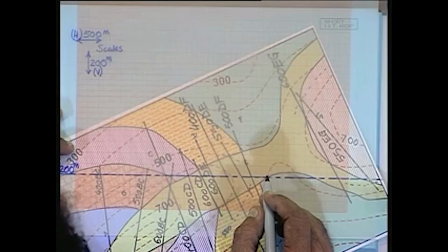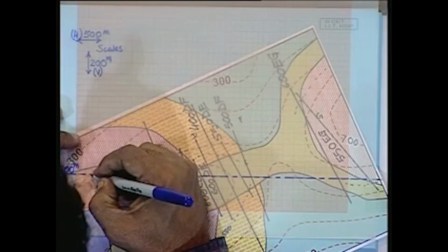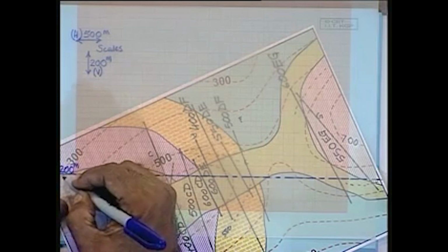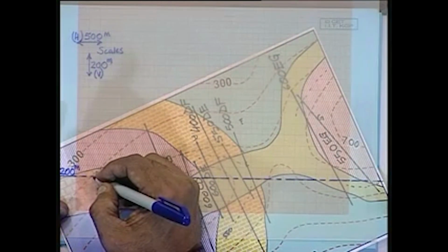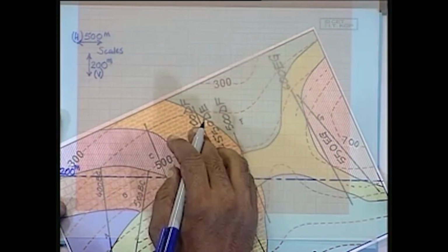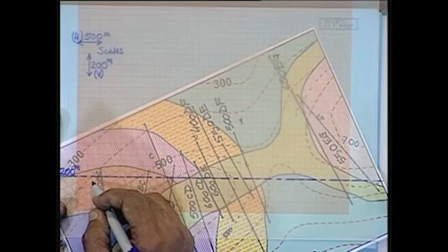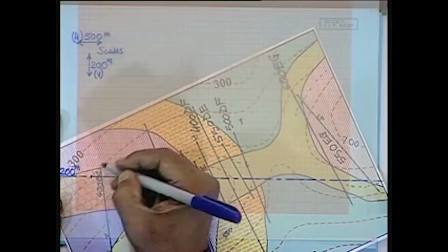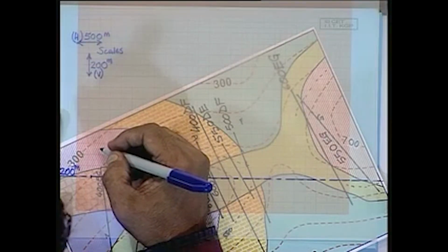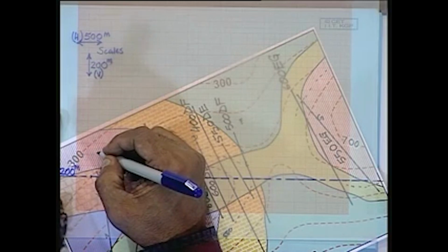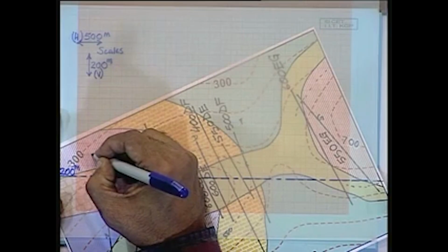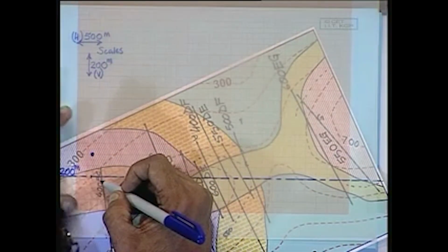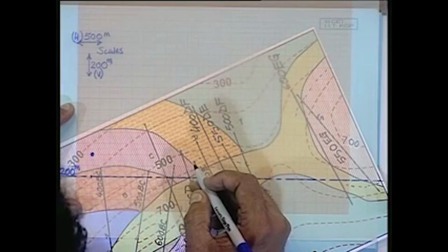All right. So let's now begin by marking the locations of the topographic contour. So first intersection of the topographic contour is at the corner, at the area which is a little bit outside of the range of the camera. So let's begin with the intersection between the section line in the geologic map and the topographic contour at elevation 400. So that is this particular point here. So 400 then, as far as our scale is concerned, is going to be at a vertical offset of 20 centimeter according to the scale that I have drawn. So that is going to be the point on the surface there.